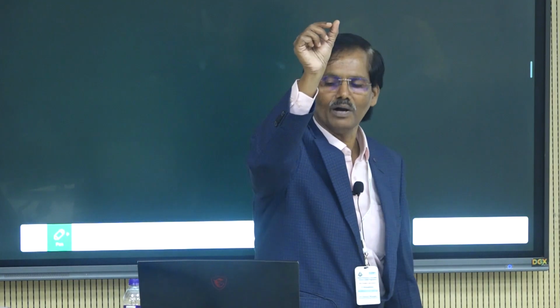This is the first approach we used to do, and this continues, right? I will not touch this, I am just saying how we used to do. Similarly, for the inertia term, viscous term, and buoyant force, there is a competition between them. Ultimately, we are non-dimensionalizing them, 1 upon Prandtl number and so on. When the Prandtl number is higher, the left hand side term goes out, and you are left with the velocity v component.